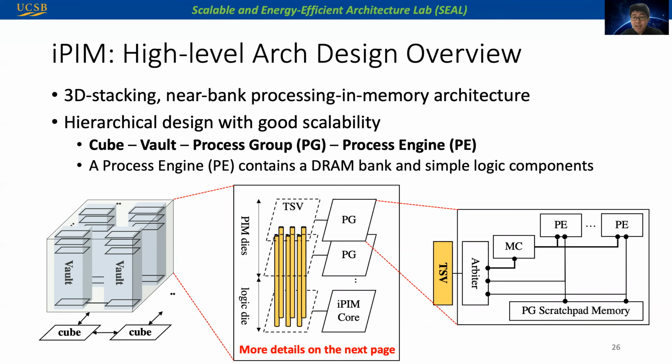This slide shows the high-level architecture design of iPIM. It adopts a hierarchical design with good scalability. On the left, iPIM consists of many cubes linked by interconnect network. Each cube is a 3D stack and is partitioned into many vaults. The middle shows the architecture of a vault, which is partitioned into many PIM dies and a logic die interconnected